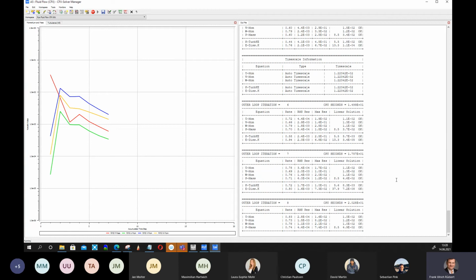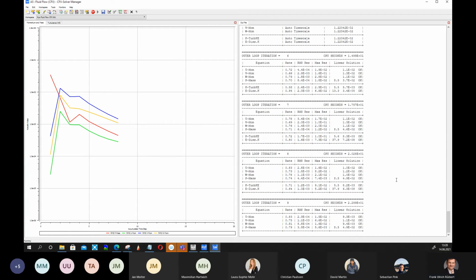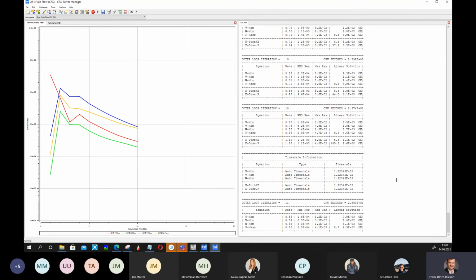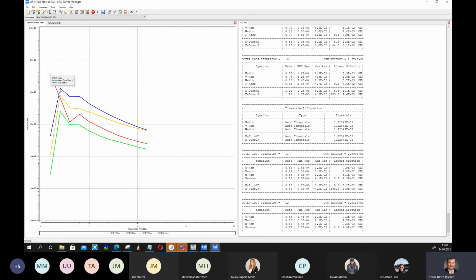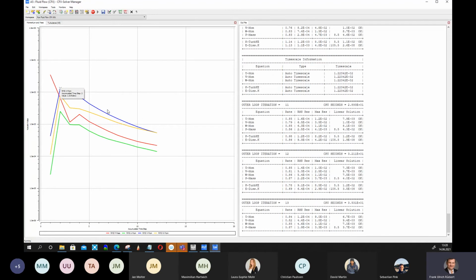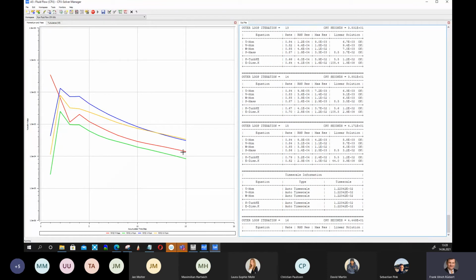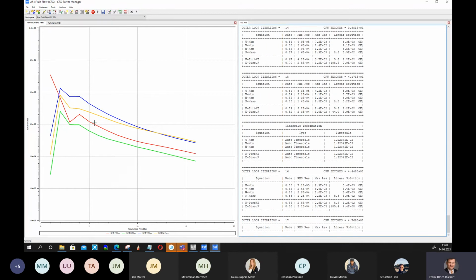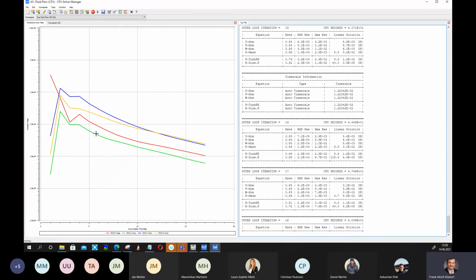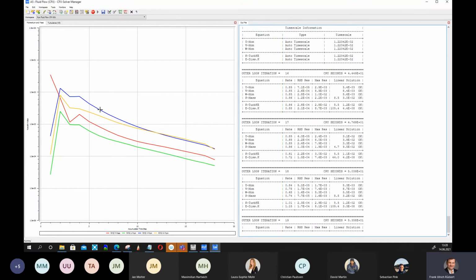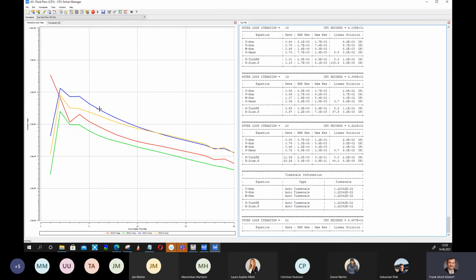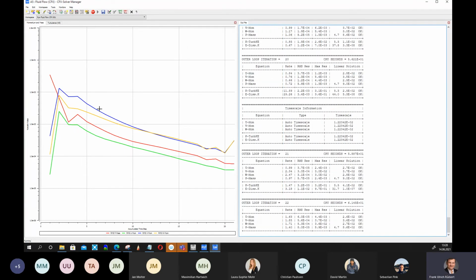You have some initialization of your field, and the solution is not really converged, so you have a bit higher residual here at the beginning. But after some iterations, residuals should go down. And again, this red line is the residual for the numerical simulation of the mass balance, and the green and the yellow and the blue lines are the residuals for the solution of the Navier-Stokes equations.